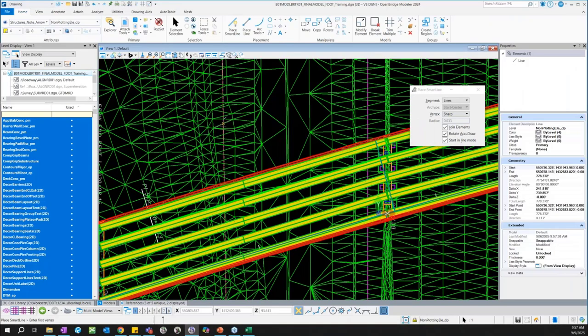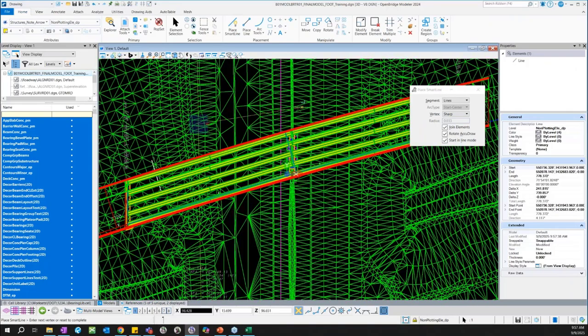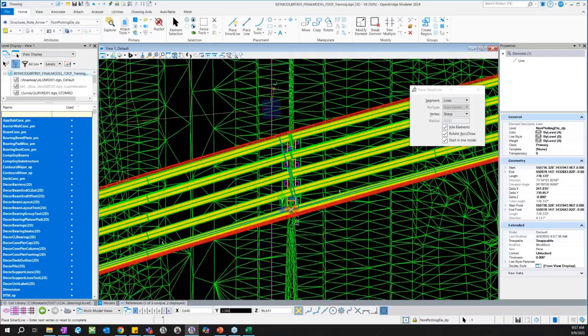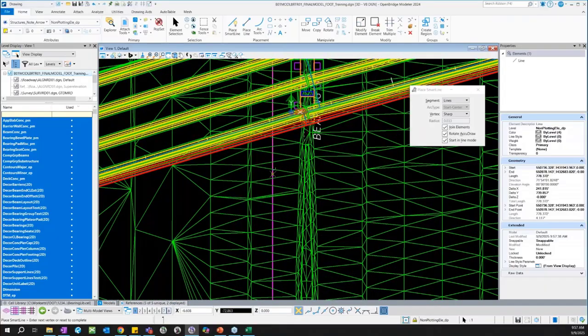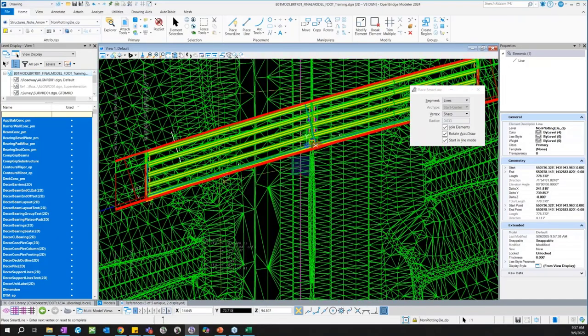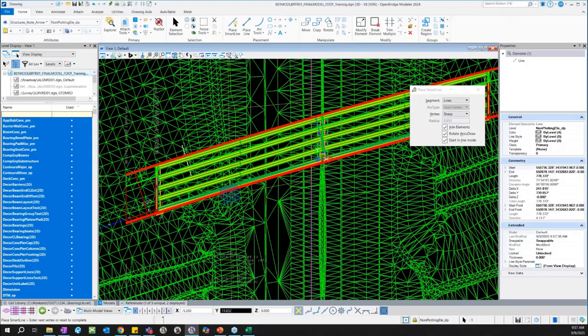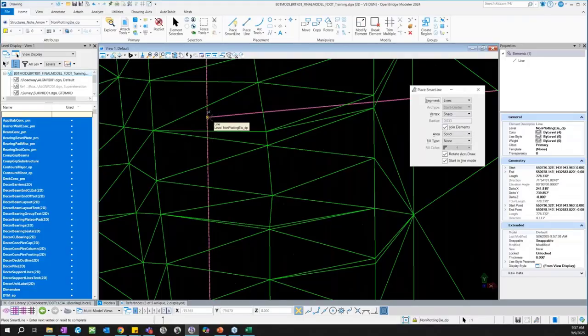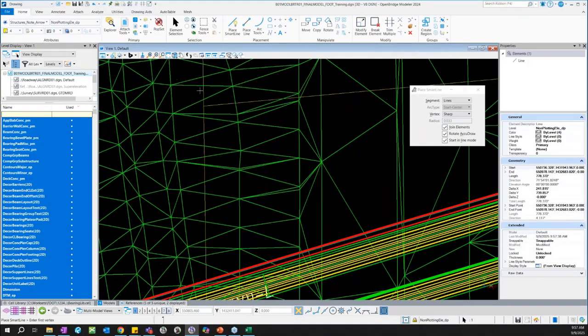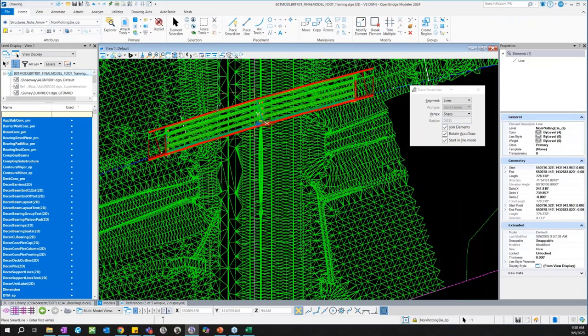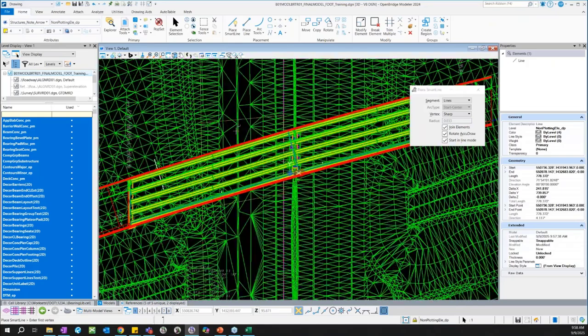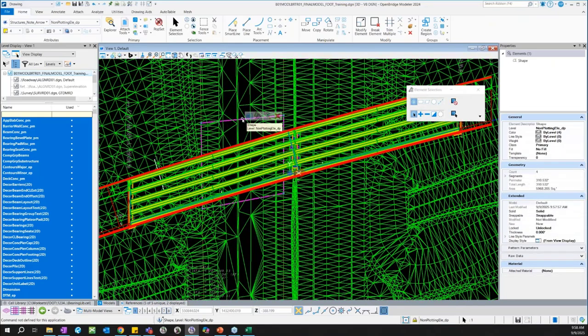All right, let's try that again. These are our gutter lines, we're going to say. And I'm using these lines because they're at 0 elevation. Otherwise, you can key in 0 for your Z dimension, and you'll make sure that you're not snapping to something that's 3D in space. So we've got this shape here.